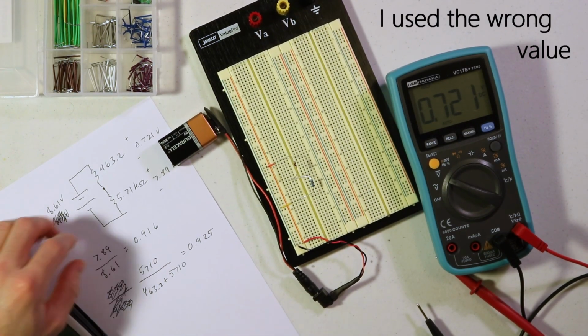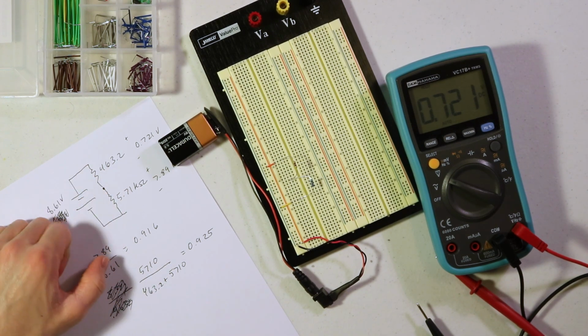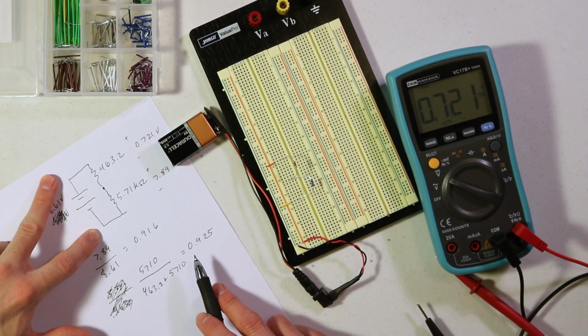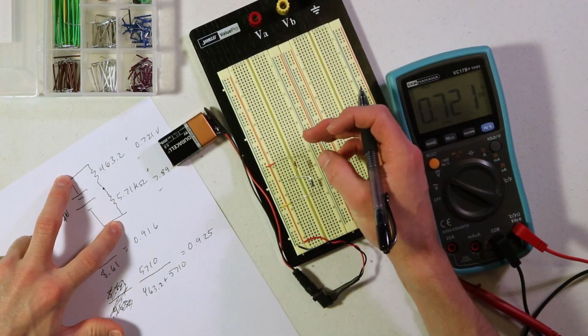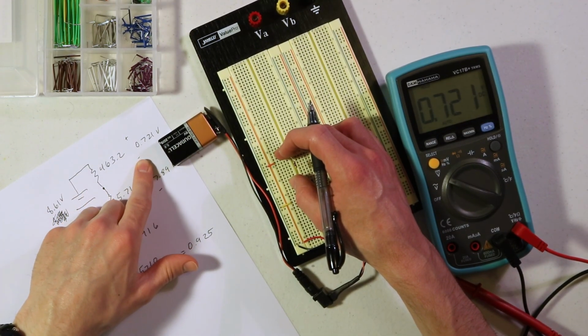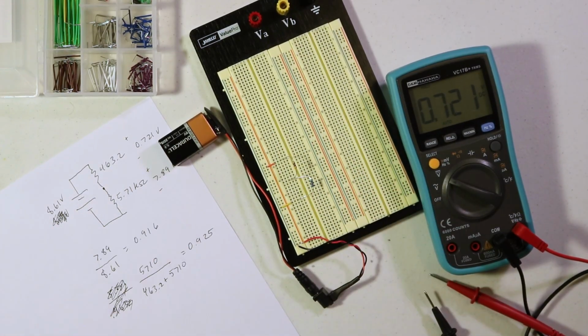But basically what a voltage divider does, you can see that depending on the ratio of these two resistors, you end up with a fraction of the voltage that you apply across that. And so depending on which voltage you want to measure, you could measure across this one and you would get a smaller portion of that number, or you could measure across the larger one and you would get a larger portion of that.